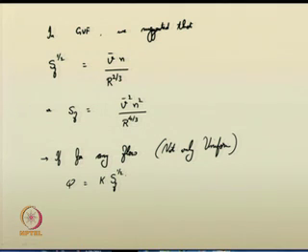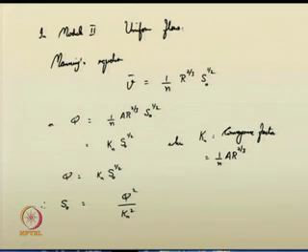If we can devise it like this, now this is the conveyance factor. This is just an empirical relationship which we formulated, and here you have suggested that this entire quantity can now be called the conveyance factor in uniform flow.